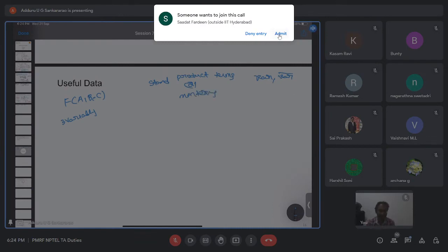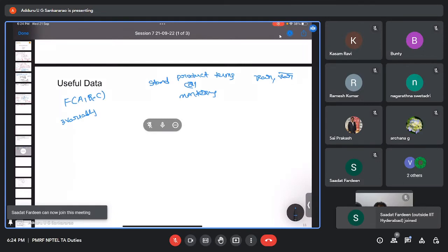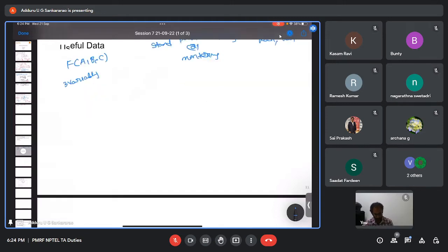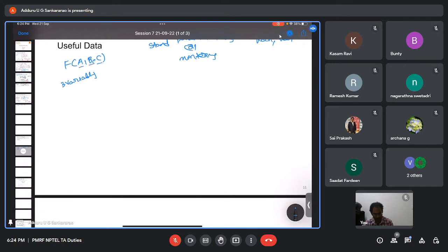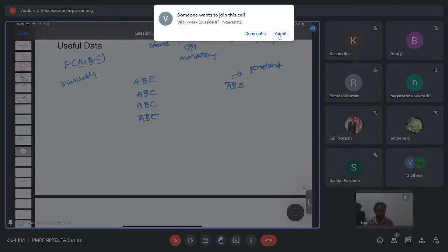Hope you have understood. They should have all the variables. They should not miss any of the variables, either in variable form or complement form. Then they are called minterms. Let us say here three variables A, B, C are there. Then something like this is a minterm, and something like this is a minterm, or A B C, or A bar B bar C bar. Suppose you take A bar B, this is a product term but not a standard product term or minterm. If it is a minterm it should have all the variables. Here C is missing, so it's not a minterm.